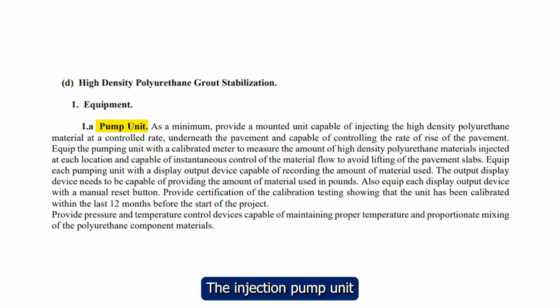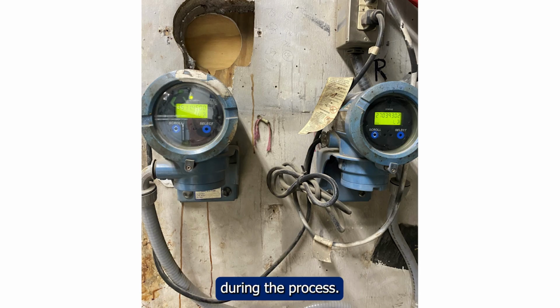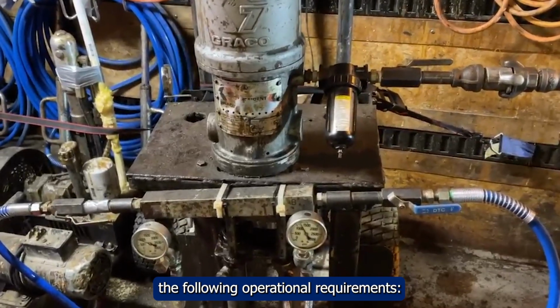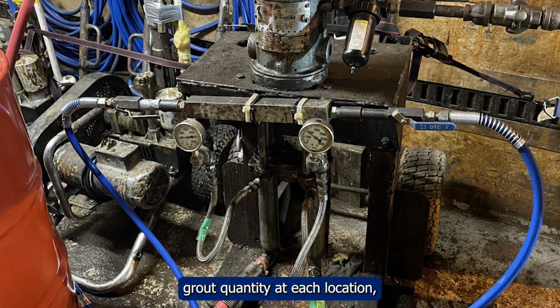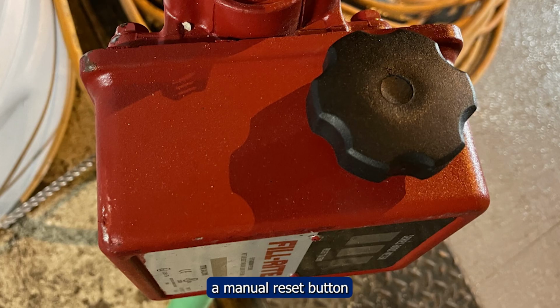The injection pump unit must be capable of injecting high-density polyurethane grout at a controlled rate beneath the pavement and must also manage the rate of pavement lift during the process. The pump unit equipment must meet as a minimum the following operational requirements. Be equipped with a calibrated meter to measure the injected grout quantity at each location. Include a flow control system to prevent excessive slab lifting. Have a digital display output showing the amount of material injected in pounds. And feature a manual reset button for tracking material totals.